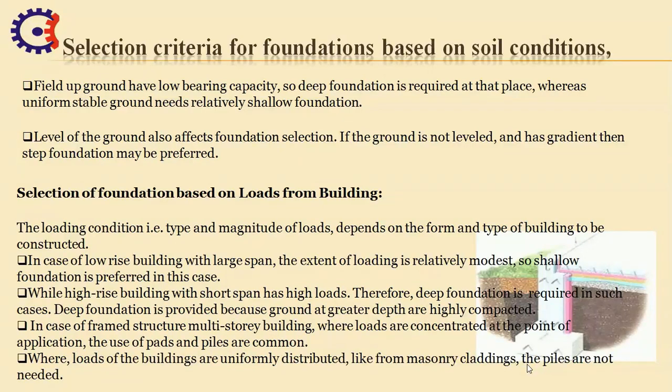If we are talking about rocks, this category involves hard sound rock, chalk, sand and gravel with little clay, and dense silty sand, etc. If this type of soil occurs, in that case we will provide strip foundation, pad foundation, raft foundation.